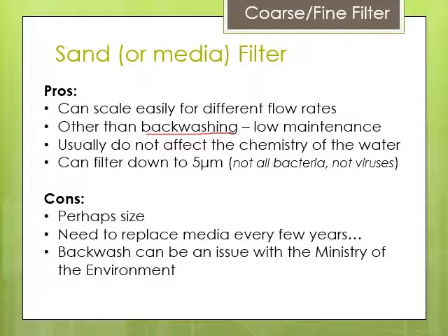There's a switch that senses when the pressure drops, and then it automatically closes the valves, reverses, and sends the water backwards for a predetermined amount of time. And then it automatically switches back to filtering, and it will just maintain itself. So you just have to keep an eye on it.